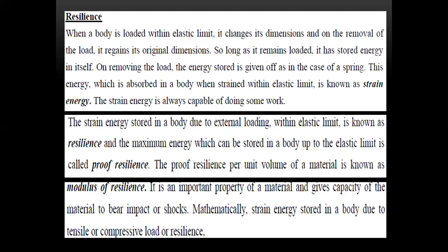Okay. Now, the next topic is resilience. When a body is loaded within the elastic limit, it changes its dimensions, and on removal of the load, it regains its original dimensions. So long as it remains loaded, it has to store some energy, right? On removing the load, the energy is given off, as in the case of a spring. This energy, which is absorbed in the body when strained within the elastic limit, is known as strain energy.